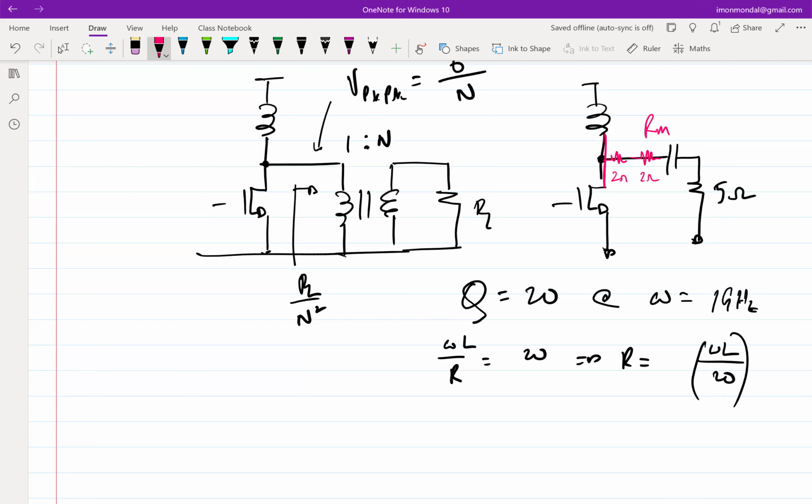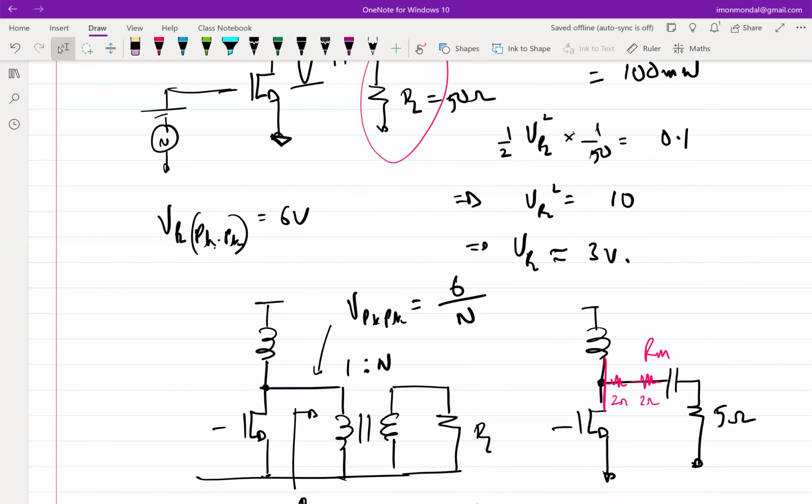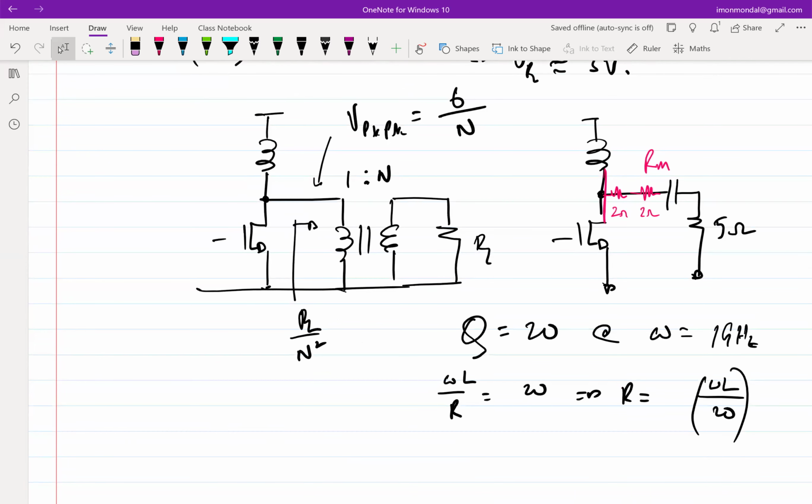So now can you see the problem? With respect to efficiency? More than 25, like it's like 4 ohm here, 5 ohm there, right? Almost 50% power is lost in your device, routing itself, right? So your theoretical efficiency of 50% now goes down to 25% without doing much. Okay.